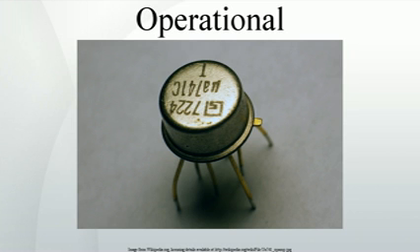Positive feedback applications. Another typical configuration of op-amps is with positive feedback, which takes a fraction of the output signal back to the non-inverting input. An important application of it is the comparator with hysteresis, the Schmitt trigger. Some circuits may use positive feedback and negative feedback around the same amplifier, for example triangle wave oscillators and active filters. Because of the wide slew range and lack of positive feedback, the response of all the open-loop level detectors described above will be relatively slow.